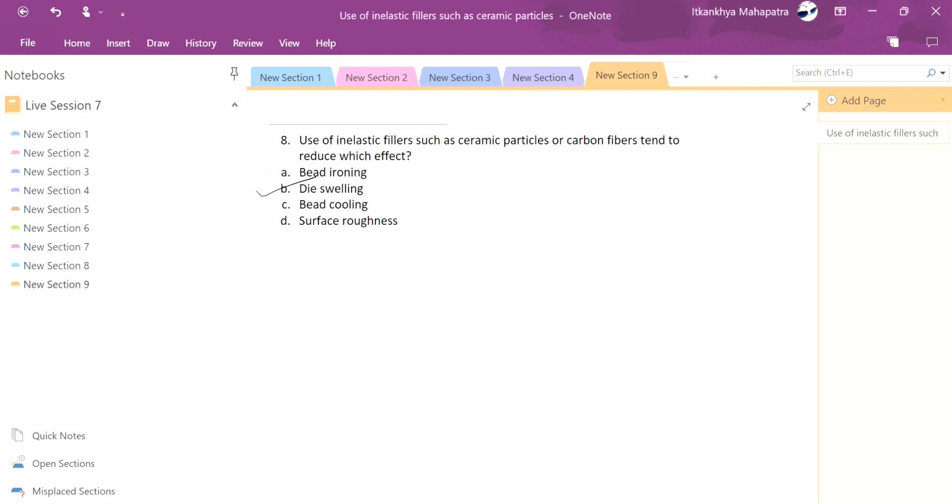Okay, so in shear thinning, viscosity decreases with increasing shear rate. Thermoplastic materials used in FDM usually show shear thinning behavior. That is, viscosity decreases as the shear rate increases. Now suppose we take the power law. We have a formula, tau is equal to (gamma dot by phi) to the power 1 by n. Here gamma dot is the shear rate, n is the flow exponent, and phi is the fluidity material constant.